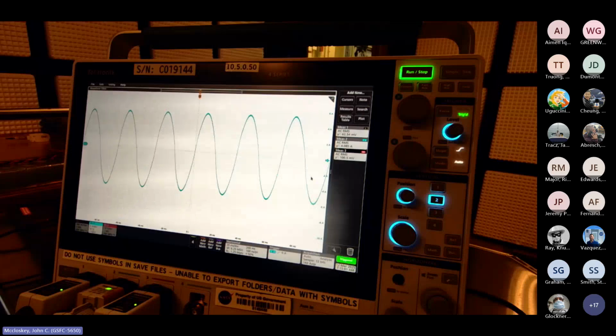So to get 1 volt across half an ohm, you would need 2 volts at the upstream side of your source impedance. So the short circuit current is going to be determined by that open circuit voltage divided by the source impedance.